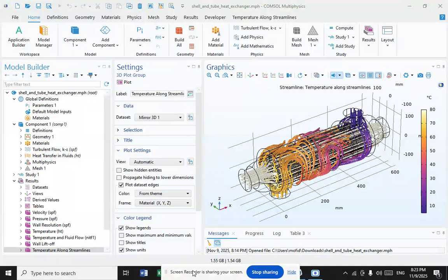However, since double pipe heat exchangers are simple, they are used to teach heat exchanger design basics to students, as the fundamental rules for all heat exchangers are the same. The first one is the double pipe heat exchanger. One fluid flows through the smaller pipe, and the other flows through the annular gap between the two pipes. These flows may be parallel or counterflows in a double pipe heat exchanger.